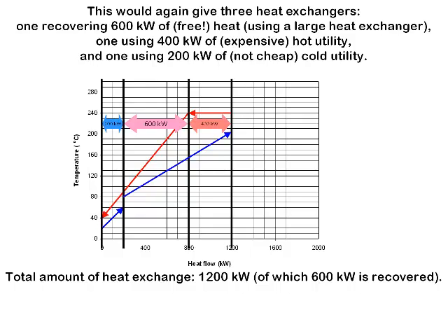Notice now that the total amount of heat transfer that is occurring in our system is 1200 kilowatts. So once again, we're no longer exchanging heat unnecessarily. Our starting point was 1800 kilowatts of heat transfer that needed to occur. We've reduced the total amount of heat transfer to 1200 kilowatts because we're recovering 600 of that.